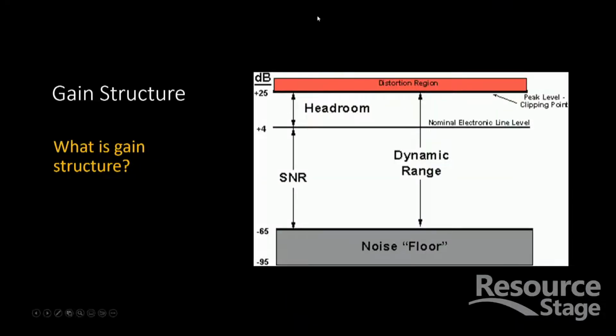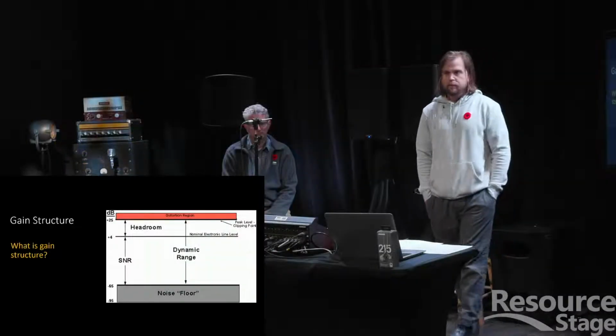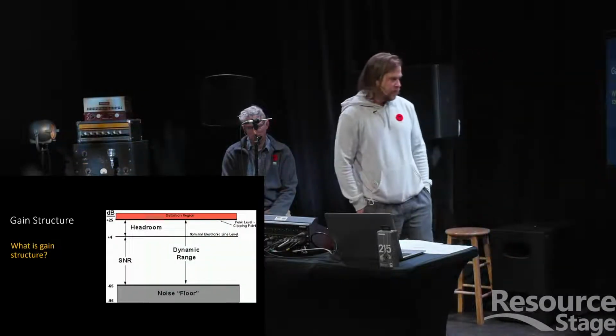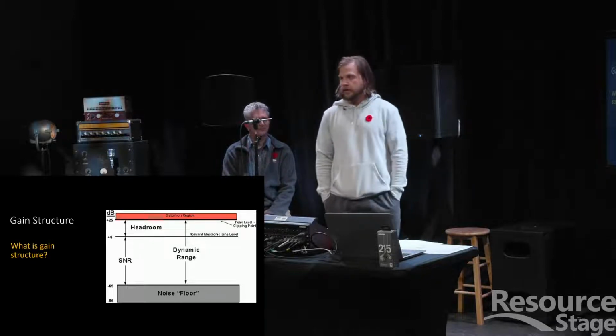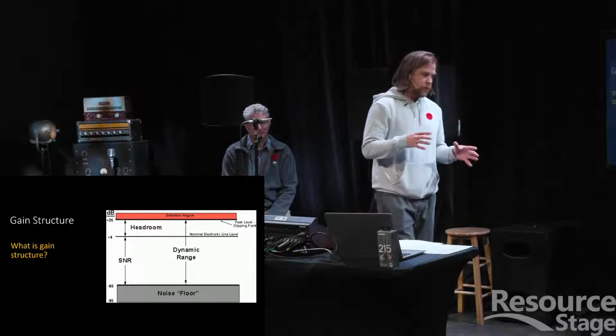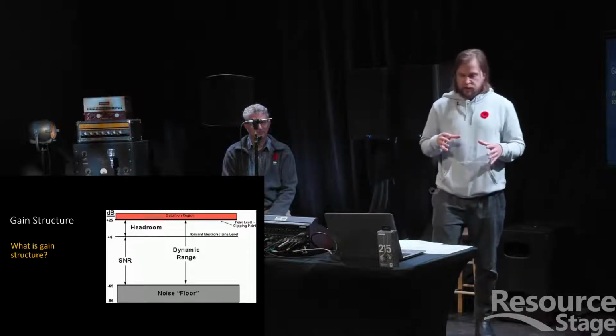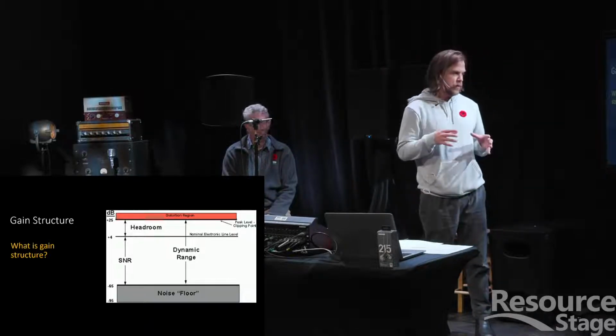So what is gain structure? There's a couple of things we probably want to define first. One being the noise floor. Any given piece of audio electronic equipment is going to have a noise floor. It's going to have an operating level in which the components are going to make a certain amount of noise.